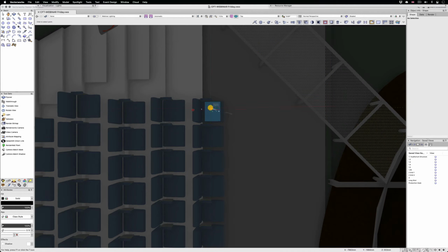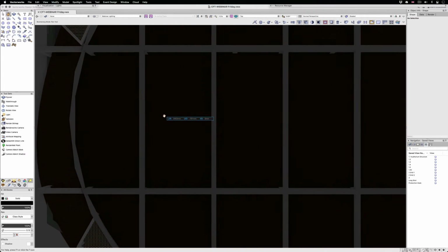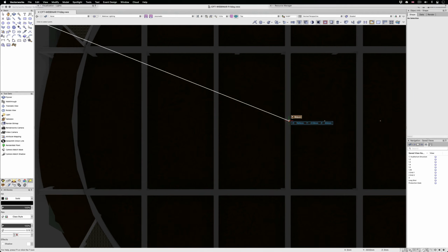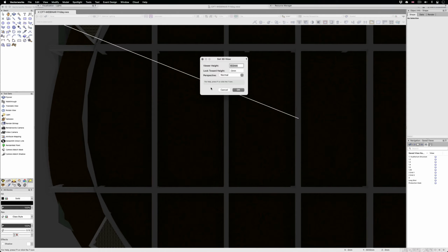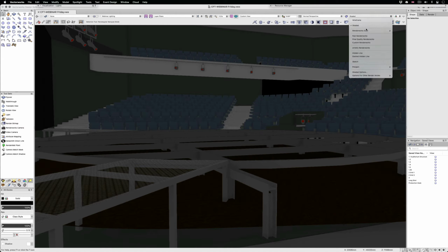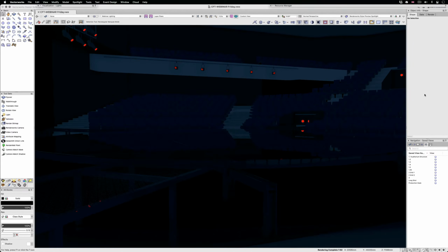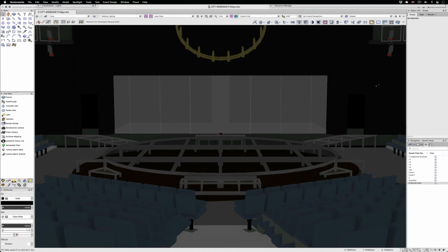So the first click of the Set 3D View command is the viewer's lens, and the second is any snap point you can find in 3D. When you make the second click, you'll be asked to confirm the measurements the command has taken, and then you are instantly taken to the seat that you specified. When I rendered the view, I can see that in actual fact I've got lucky, and the lenses of the lights are just out of view on the glass. Now that is done, I go to a view of the stage from the production desk and run the RenderWorks style again.